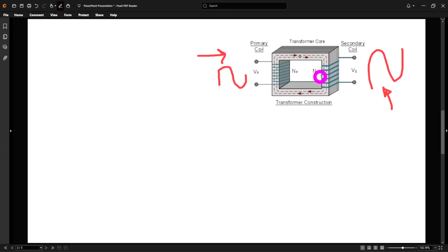And even if we could make a transformer extremely large to go to very low frequencies, the core would become so huge that it would not work at higher frequencies, aside from it becoming completely impractical. There will also be magnetic flux saturations and other problems with transformers as a result of that. So even if we could solve the self-resonance frequency problems of this, we would still have to deal with the extremely difficult breakdown problem of generating plus or minus 20 kilovolt on the secondary side of this transformer and the isolation to the primary and so on.